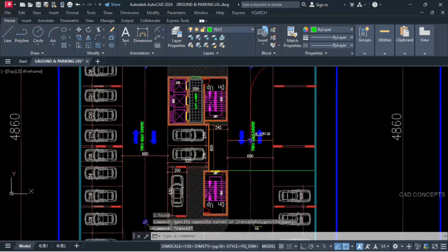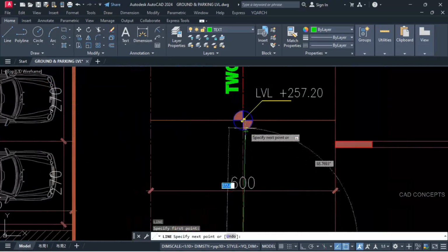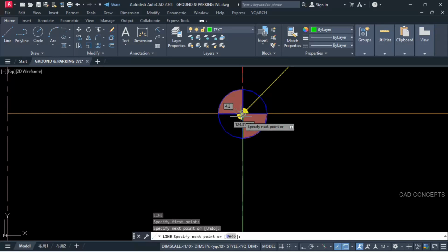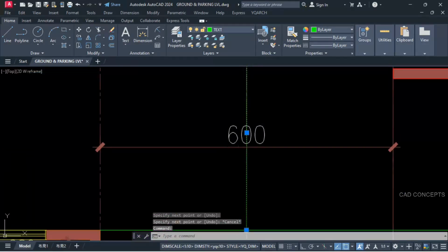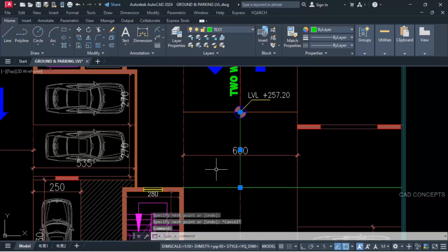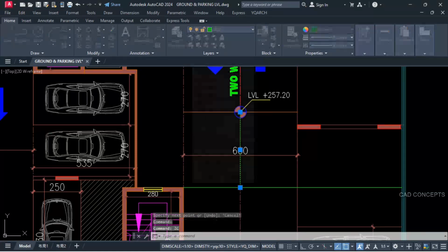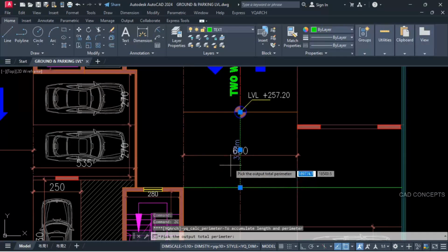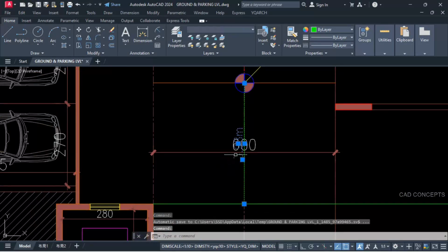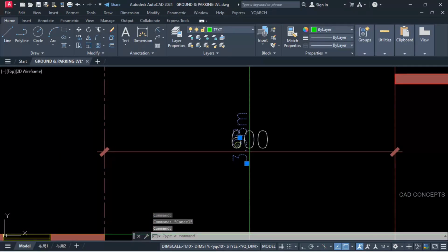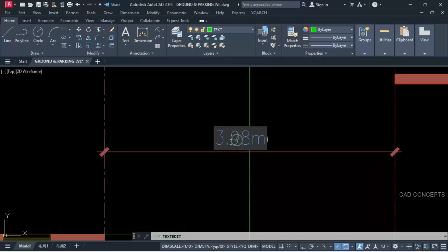So let this portion all be removed. Now this much extension will continue at 14%, got it? We are adding this much also straight at 14%. After that, rest all will go 4%. So we are getting 398 centimeter. You can consider 400 centimeter for our 14% slab also.